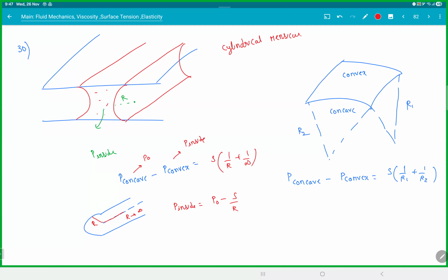That is the reason. Did you ever notice this? When you have plates placed in water, when you take out the plates, sometimes the plates stick together. Kabhi dekha? Meaning it used to happen a lot in our hostels and IIT mein. They used to have a big tub and they used to just put the plates inside. So when you try to take out the plates, two plates used to come out. Between the plate and the plate, the thin film of water used to get stuck. And because the pressure is less, the atmosphere is pushing from both the sides. They used to get compressed. So you need to put a small gap and let the air enter inside and then it comes off. Clear with this?